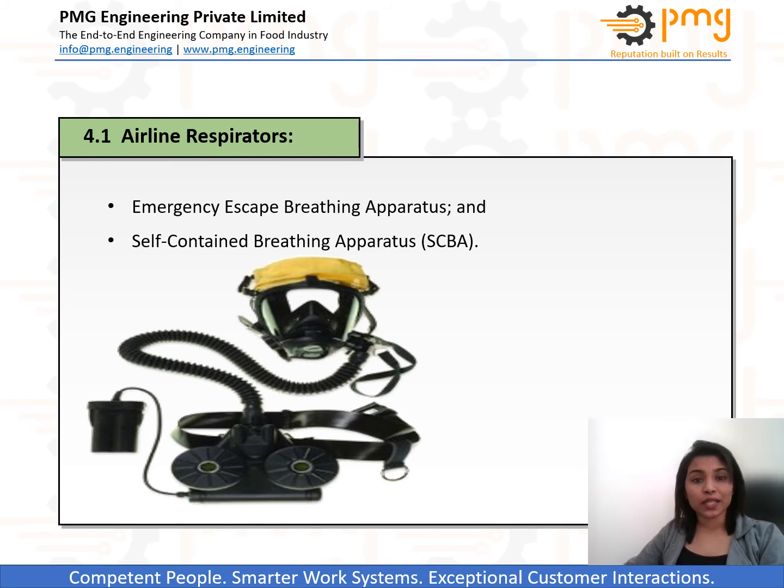A self-contained breathing apparatus, SCBA, typically has three main components: a high pressure air cylinder, for example 2200 psi to 4500 psi, a pressure gauge and regulator, and an inhalation connection which includes mouthpiece, mouth mask or full face mask. These are connected together and mounted to a carrying frame or a harness with adjustable shoulder strap and belt, so it can be worn on the back. There are self-contained breathing apparatus, while supplied air respirators make use of a hose to deliver air from a stationary source.